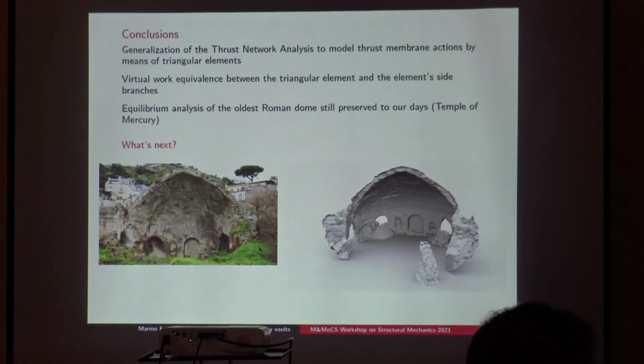I have a question concerning, I'm not sure if I understood you correctly. Did you add an additional membrane stiffness, or did you just have the thrust forces? Do you just recompute the equivalent membrane stresses? So first of all, I don't add any stiffness because I don't have material information regarding the vault. So there is no stiffness involved in this formula. We have only equilibrium equations.